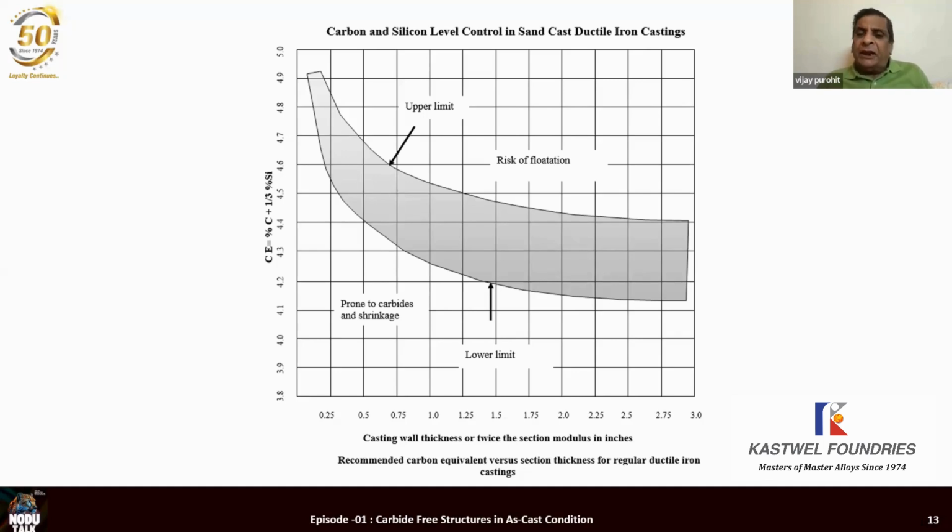And you will see, you take any casting in your foundry which you are making today, and you go to the pattern and you check the fillet on the pattern with the help of the radius gauge, and you check the same radius on the casting which is made from that pattern, same cavity, and you will find that the radius on the casting is at least half, if not less than half, the radius on the pattern. Though in SG iron casting, the radius always shrinks.